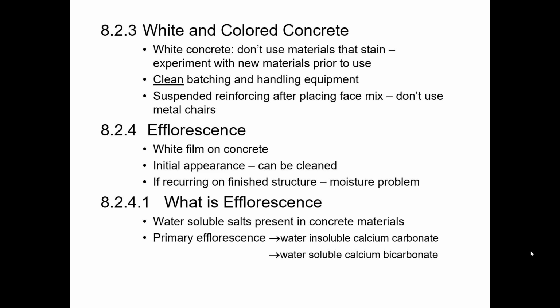On a more technical level, if you ask the question, well, what is it? What causes it? What's happening is you have these water-soluble salts that are present on a molecular level in the different materials that make up concrete. Those could be present in either of your aggregates. Sometimes those are present in the cement, usually not, but could be. Sometimes those are present in the actual mixing water to a small degree.